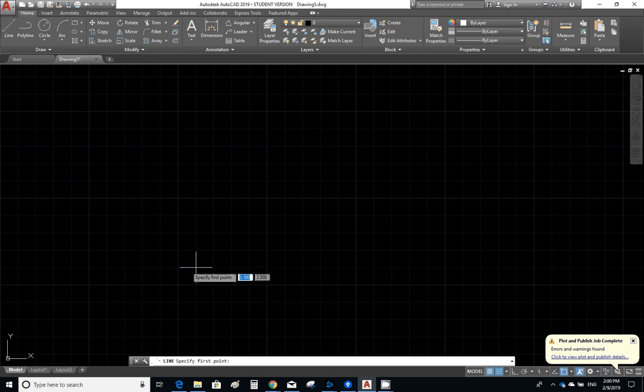The snap distance and the grid distance can be specified separately, and the default value for them both is 0.5. It's 0.5 of the units we chose. In case our unit here is 1 meter, the snap is up to 0.5 meter. It's helpful in drawing. Very helpful actually.